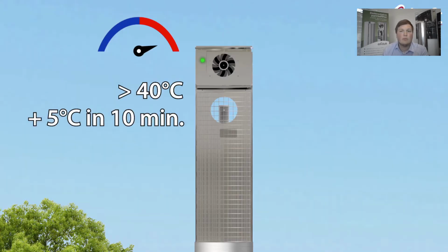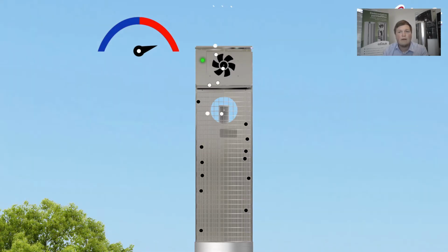Normally the filter will be in an idle state, and there's a temperature sensor inside the filter at the bottom, and when it sees an increase in temperature, it will turn on the filter. So the filter will turn on automatically shortly after the fire is lit inside the fireplace. Together with the filter, the built-in chimney fan or draft booster will turn on and make sure there's a steady draft inside the chimney.